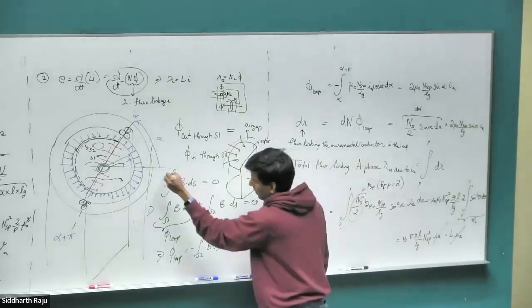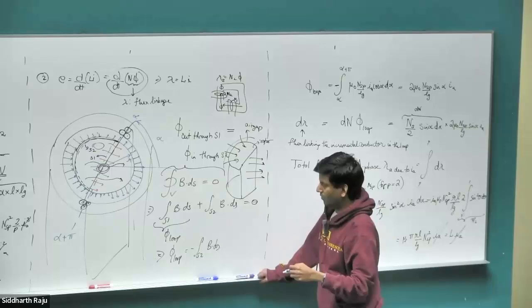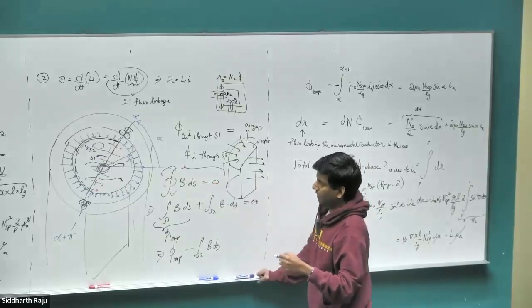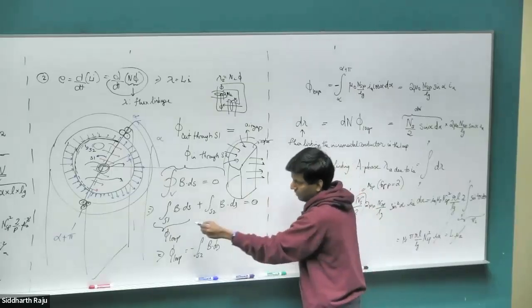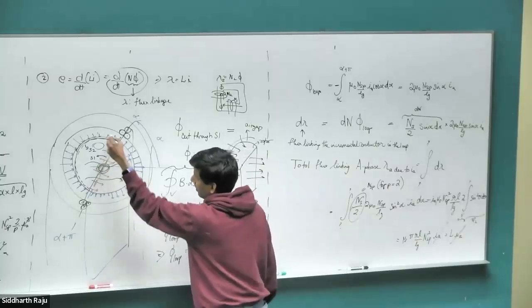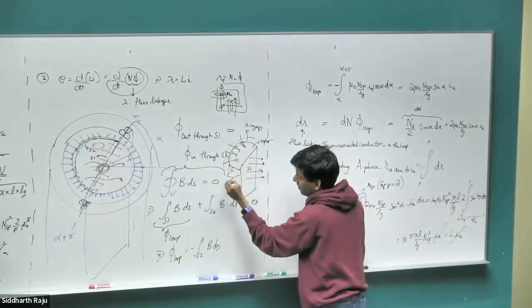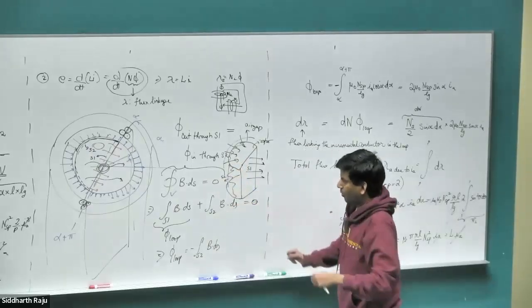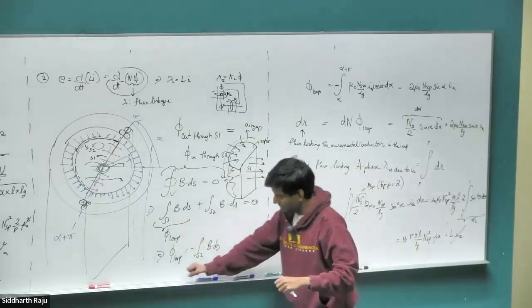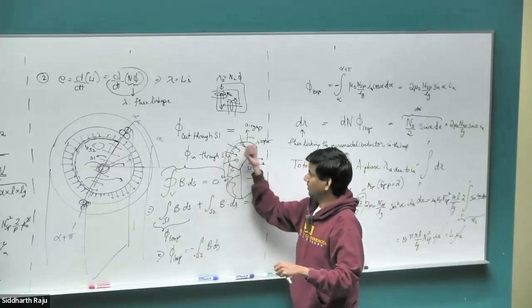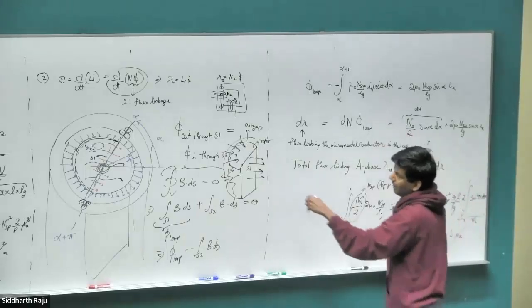Right, and this comes from our Gauss's law for magnetics. If you go around a closed volume and integrate the magnetic field, you would end up getting the net to be 0, because there are no magnetic monopoles. Whatever field lines leave must be the same field lines that come in. So putting that into this expression here, let's call this surface 1 and that one surface 2. So this is surface 1. This whole thing is surface 2, like a paper bent over. And if you do the summation of these two, that should be equal to 0. So the flux leaving the loop is just going to be the negative of the flux entering from this side on the surface. And that is a pretty simple problem to solve, because we know the field at every point in the air gap, right?